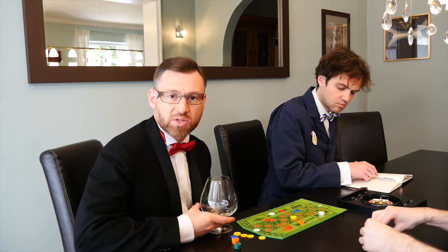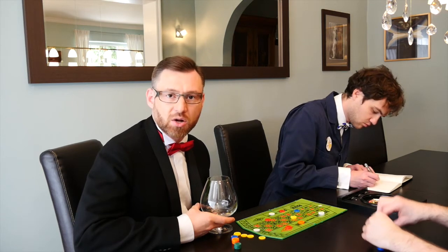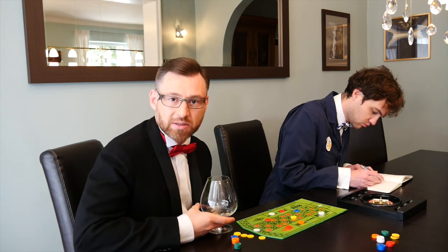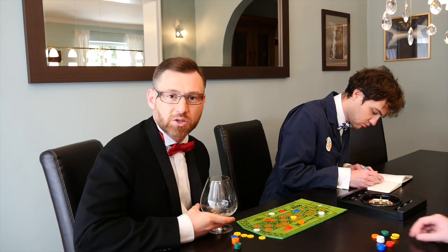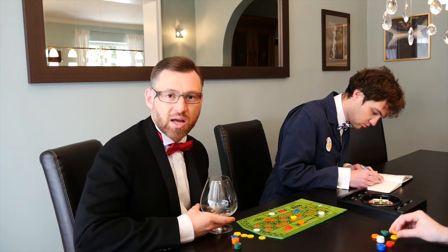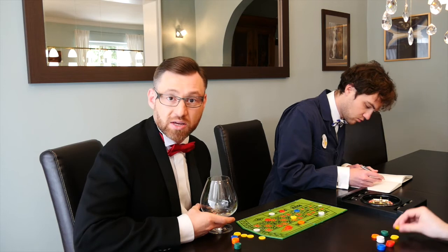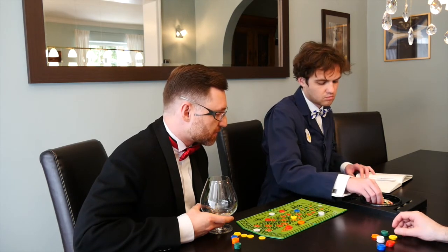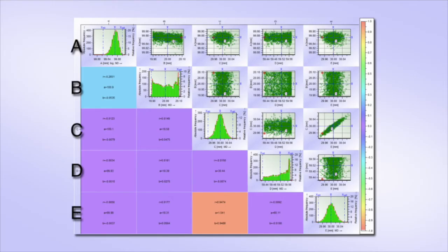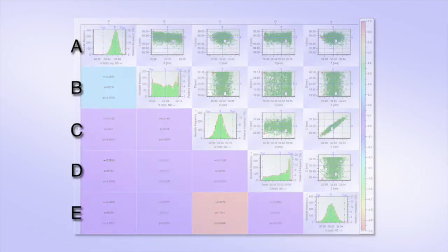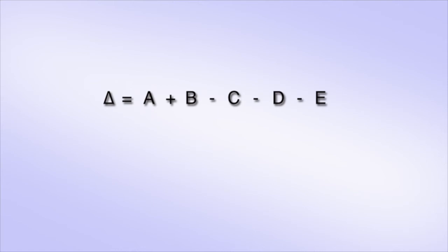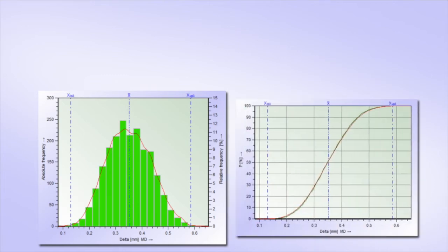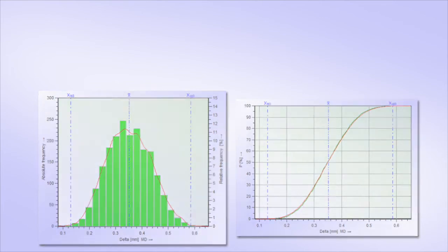The randomness, of course, has its specific properties corresponding to the properties of the tolerances. In this way, we can generate various distributions and also their mutual correlations if needed. For each of the simulated cases, we can calculate the resulting specification parameter and evaluate all of them as a statistical sample. This sample will then show if the risk of being out of the desired specification is low enough.